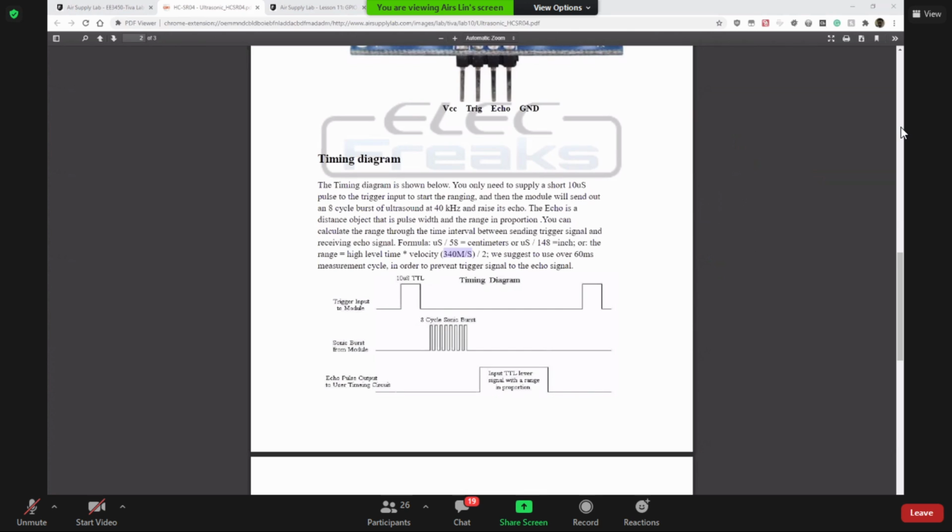Okay. So you want us to fill the blank right now? Oh, depends on you. Okay. You just have to know. So if you want to fill the blank, that's fine. Or you want to do this one later, that's fine. So you just need to know. What trigger, right? Which pin do you connect to trigger? PF3, here's F, and it's pin 3. Then on the big board it is PL5, so this one should be GPL and the 5. Okay. And also, yeah, you should know how to do this one. And also finish the configuration for the setup that you want.